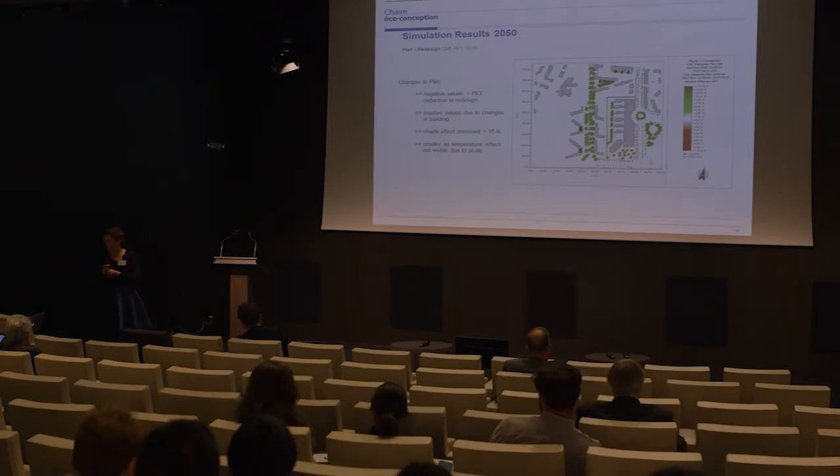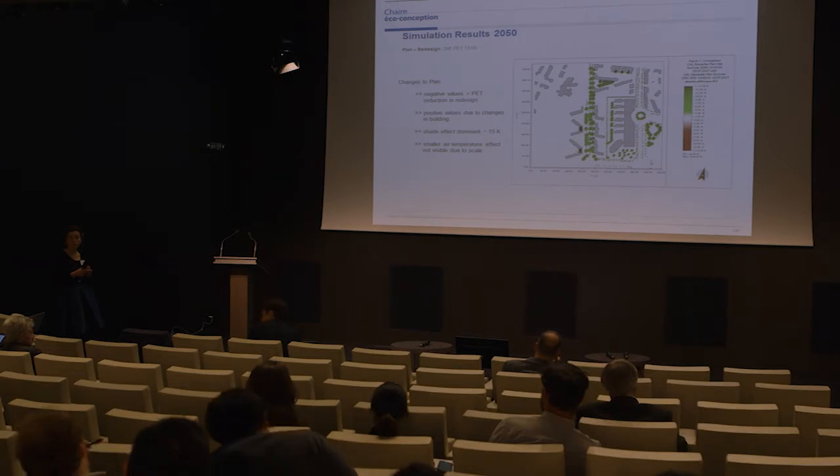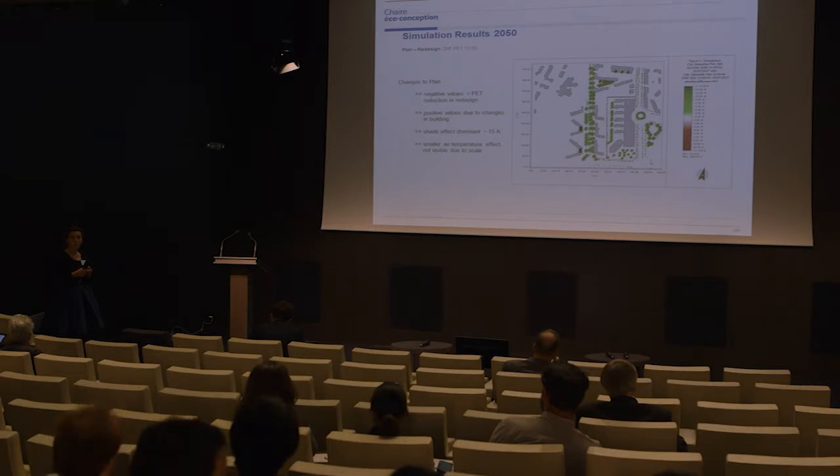Yeah, so that would be then a question for the building energy design people. So we have a very simple one-zone building model. So we can say what are the heat fluxes through the walls and the windows, and what energy input is inside the building. But it would make no sense to say this would result in this and that air temperature in the different zones. So for that we would need an advanced building energy simulation model. But for that we can provide the boundary conditions then.